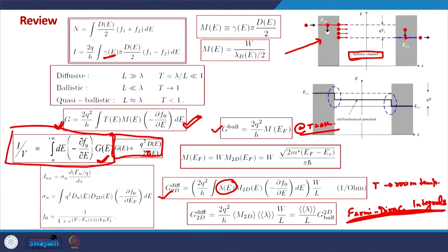Okay. Similarly, in a ballistic device, the voltage drop is equal to the conventional voltage drop, but the voltage drop now happens only on the contacts. The voltage drop does not happen in the channel. So, the resistance of a ballistic channel is because of the contact, or because of the interface between them, and this is accounted for by the contact and channel combination essentially.